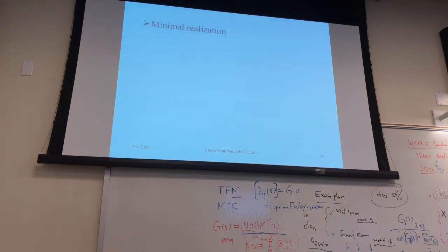So how to do minimum realization? This is not minimum, but this is a very convenient way to have a realization, and yet it's controllable or observable, but not both. Okay, so it's not bad. I have a way to do it. Otherwise, if you don't have a systematic way, you cannot even know where to start. But it's better to have a minimum realization.